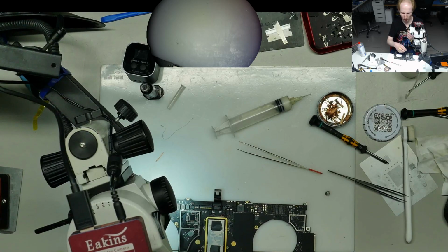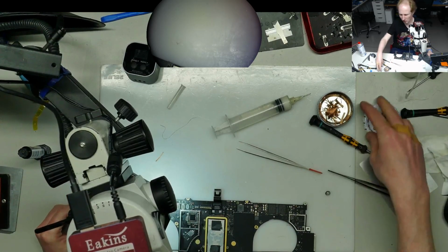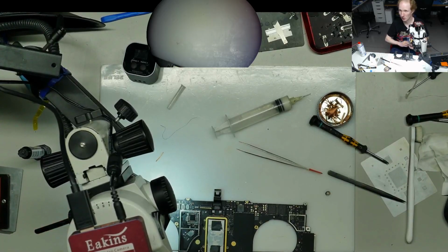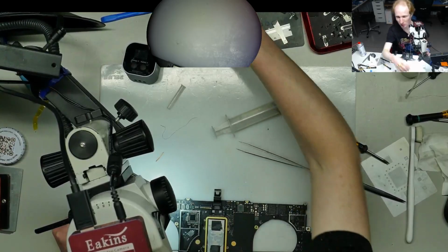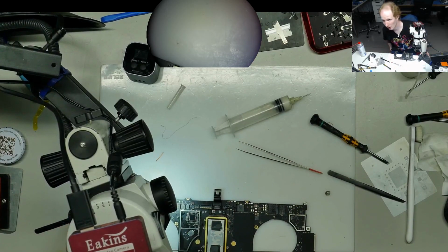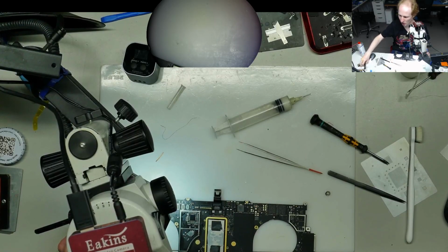There are so many I2C lines, like there are I2C lines to the display, to the camera, and so on. So you can also listen to the camera and see if the problem is with the camera itself, with I2C line to it, and so on. So a very powerful tool, actually. Just like $5 or $10 for the very simple analyzer with like 8 or 4 lines, and this is more than enough to analyze this stuff.